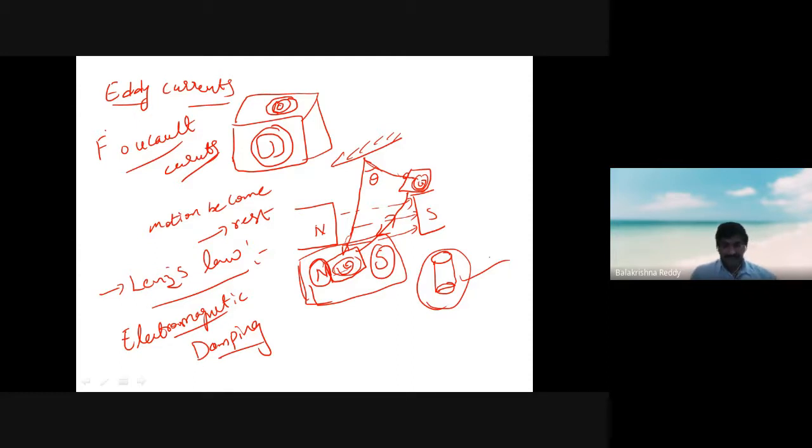In this case, in the core part of the material, since the currents are developing in a circular path, these currents will again induce some more magnetic fields, which are opposite to the change produced in itself. Who has produced the change? The input magnetic field. Who is the input magnetic field? The north and south poles which are taken initially. So this is according to Lenz's law.